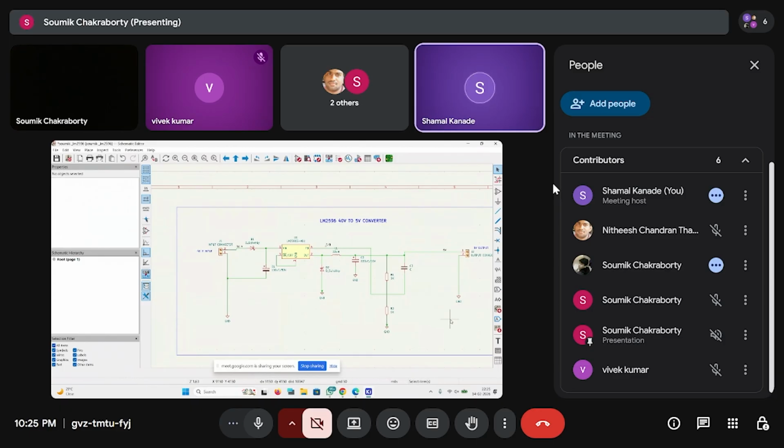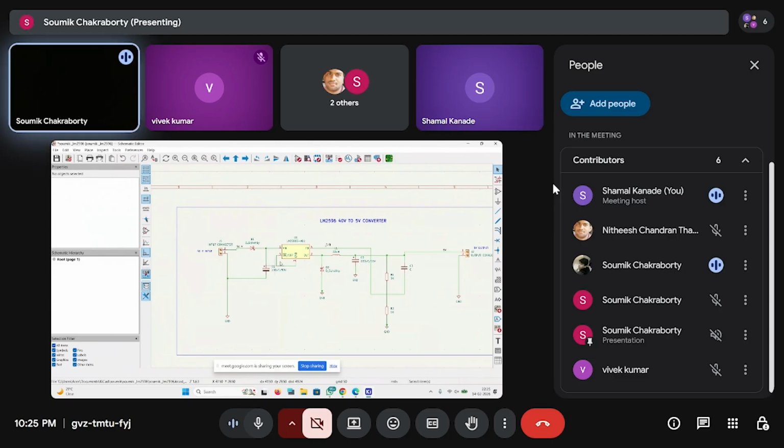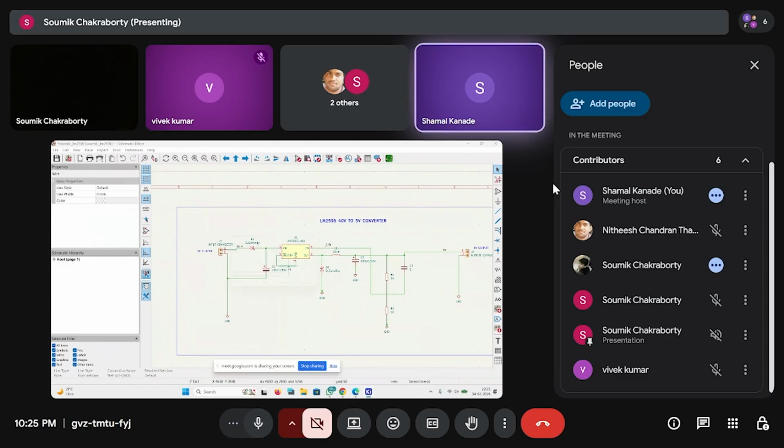In pin number 3 and 5, on/off is connected, but where is the ground? The ground is not connected on pin number 3 and 5. Ground is also needed on pin 3 and 5. Otherwise it's only floating, with 3 to 5.